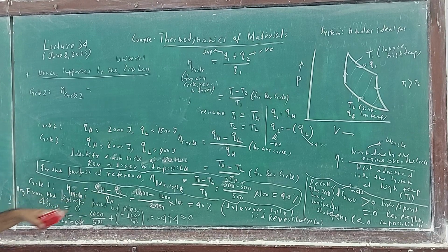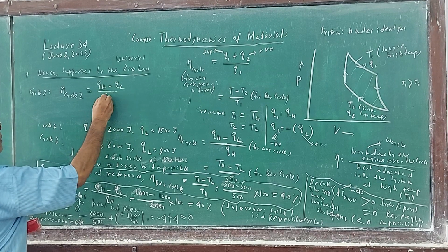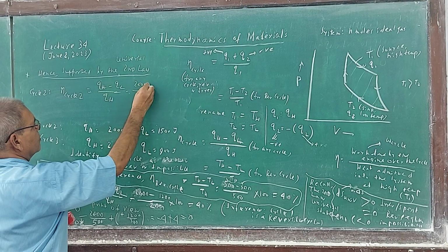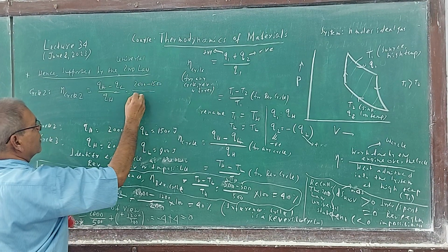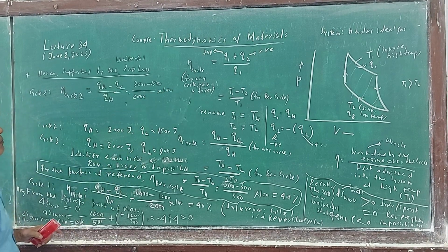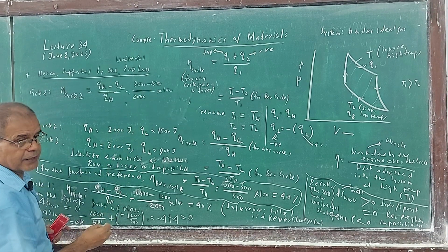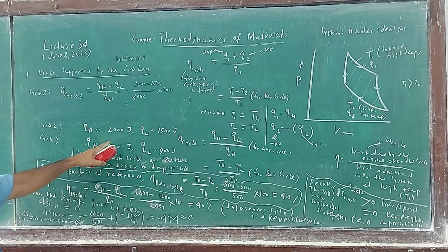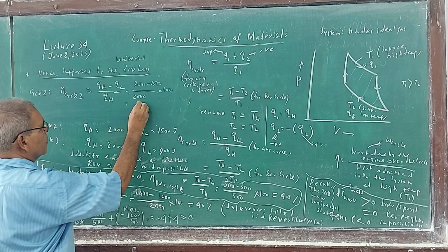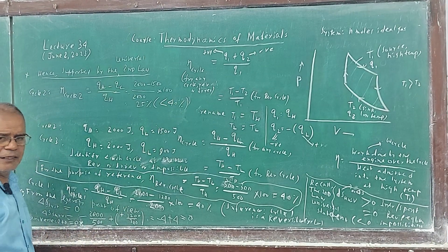So first, QH minus QL over QH, as you did. What are the values? 2000 minus 1500 over 2000 times 100. What is this value? It is 5 by 20, which means 1/4, 25%, which is less than 40%. So it is acceptable.